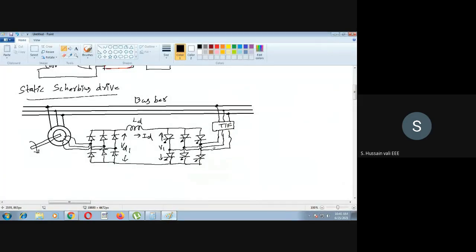Main conversion is happening through the power electronic devices. I will show you here. See this once again, same thing. You give the power to the stator. This is the stator. Then the rotor does some work. Other than that, you call it S into P_AG, that is the air gap power, that is the slip power. So this slip power you tap here and send to this three-phase bridge rectifier. Then what does this three-phase bridge rectifier do? It converts this AC to DC.